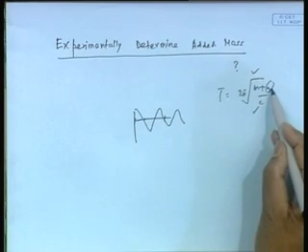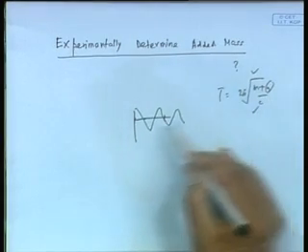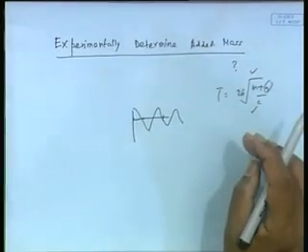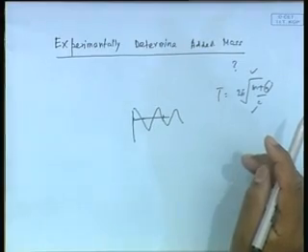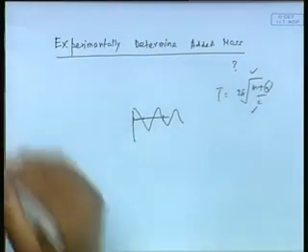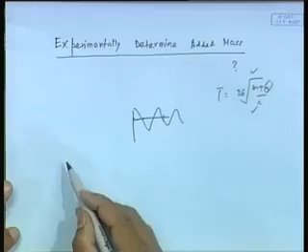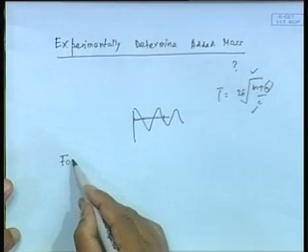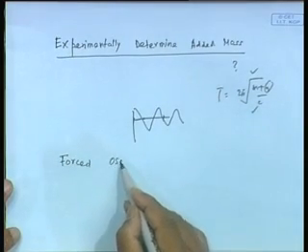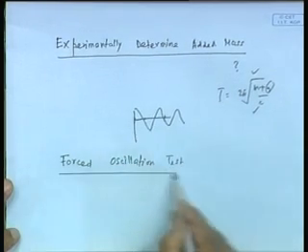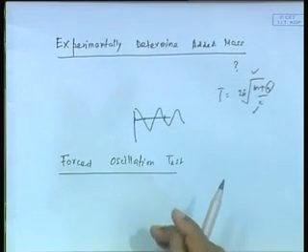What is wrong? What I found out this is only for this period. Remember, this A is a function of frequency. See, I have no choice on the frequency period. Let us say it is 11 second, scale down version maybe 3 second. So, what I found A is only for 3 seconds. So, in order for me to find out added mass, which is over all frequency, I have to conceive a different experiment. Okay. Very important to understand that. So, this is what is called, what we are going to talk to a little bit, is called forced oscillation test. In only one mode heave I will tell, forced oscillation test.